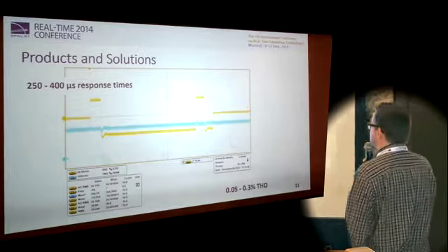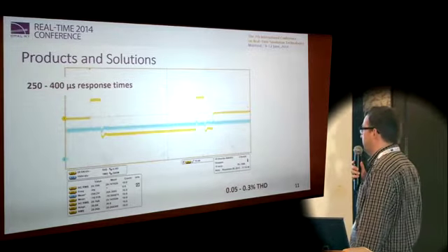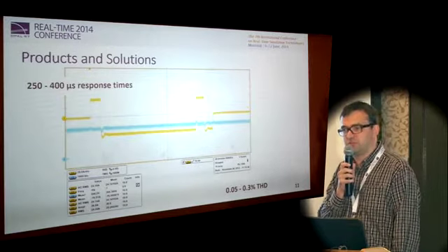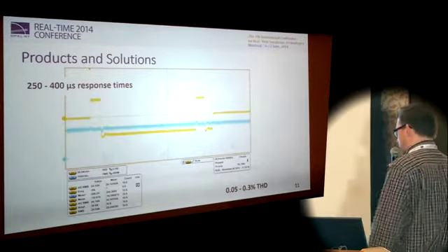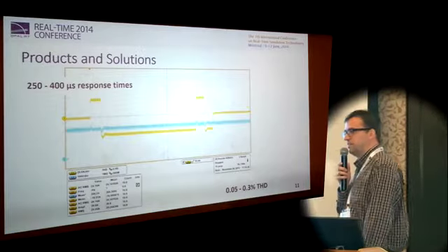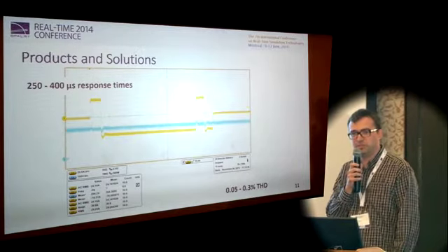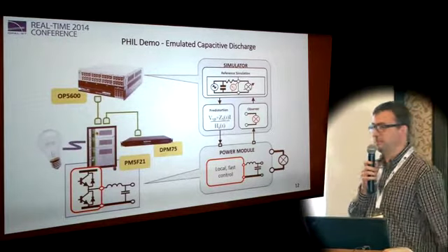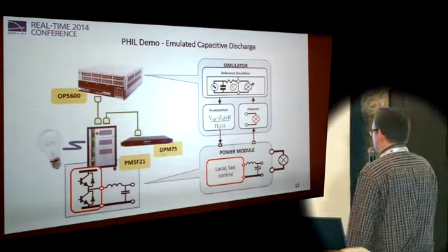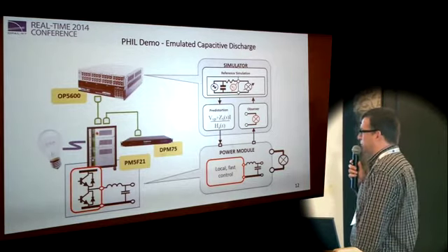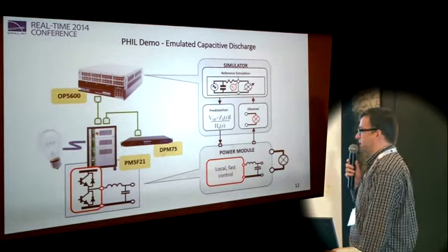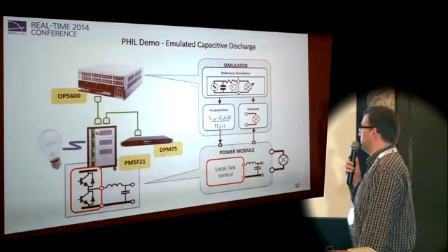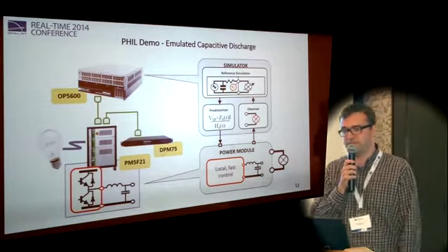So now about the demo case that we are giving. Basically, we have chosen a visual demo being capacitive discharge through a light bulb. So the device under test is a very sophisticated device that you won't find easily anymore in Europe. It's a traditional light bulb based on a glowing filament. And then the emulated system, which is not present, is a capacitor with a resistor and a current source for recharging the capacitor if needed.